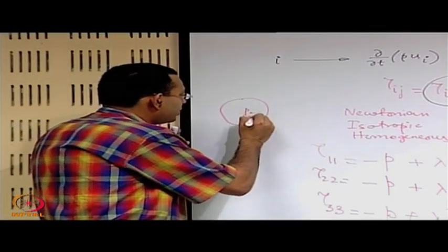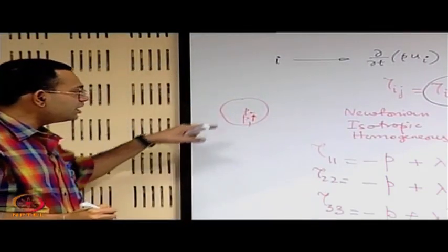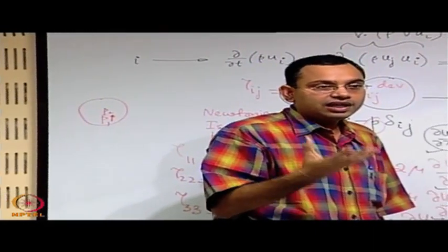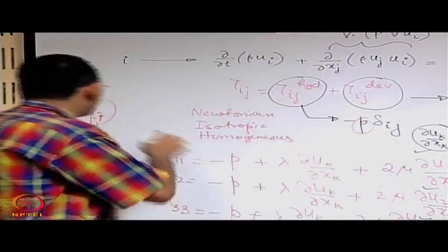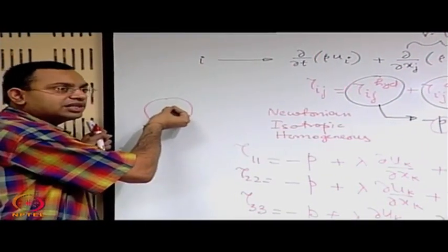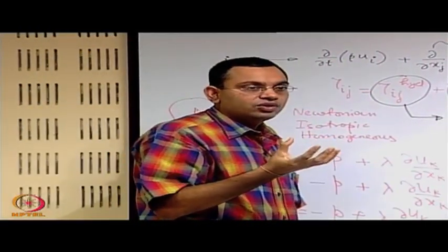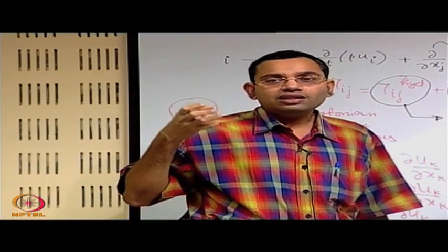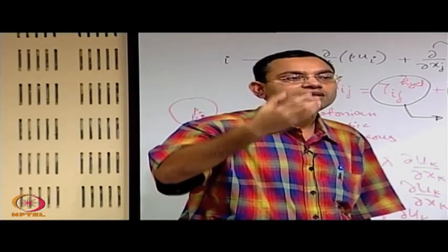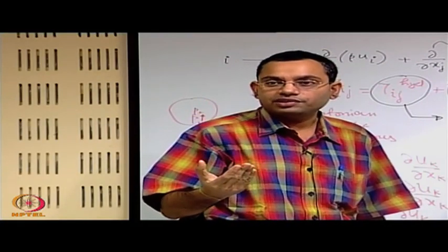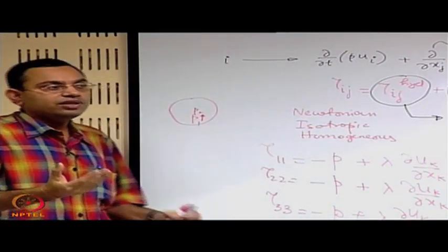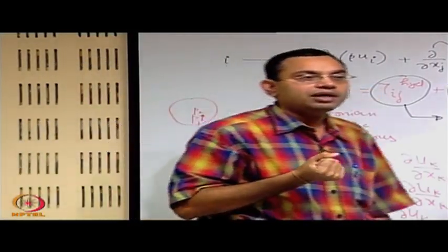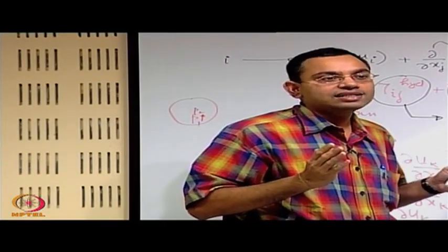So when you change the state from 1 to 2 and there is a change in pressure from P1 to P2, now if you want to have the entire effect manifested in the form of a mechanical pressure, then you should allow a time which will make it locally equilibrate. That means the sudden change in pressure because of a change in thermodynamic state will give rise to a change in vibrational mode of energy, change in rotational mode of energy, everything, and eventually all these changes in equilibrium will be manifested in the form of a change in translational mode of energy, solely manifested by mechanical pressure. So you should allow a time over which there is a conversion of all those modes of energy into the translational mode of energy that is captured by the mechanical pressure, and that requires a time. So this is called the relaxation time.